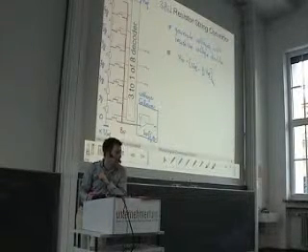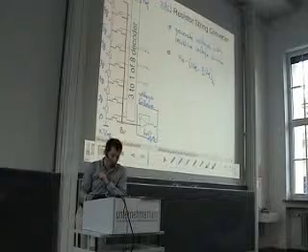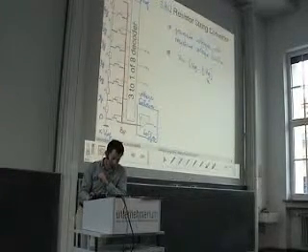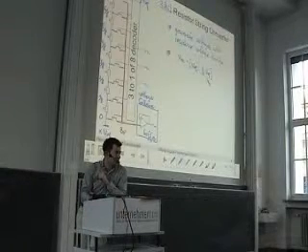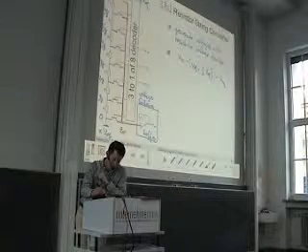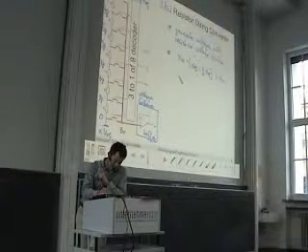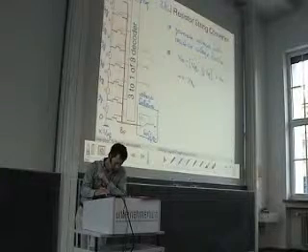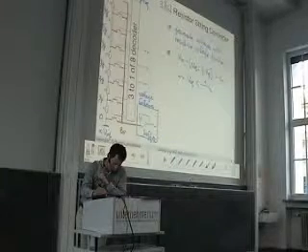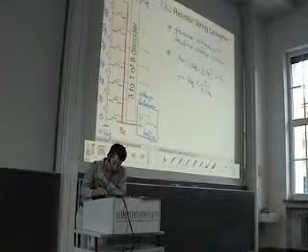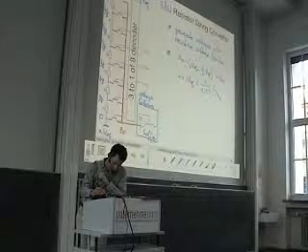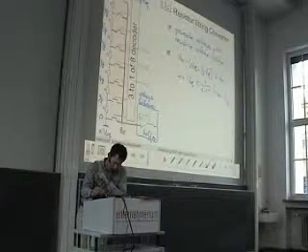This is the gate-to-source voltage that we see at this transistor: VDD minus this term. And this has to be larger than the threshold voltage. So we can say Vref has to be smaller than 1/(1 minus 2 to the power of minus n) times (VDD minus V threshold).